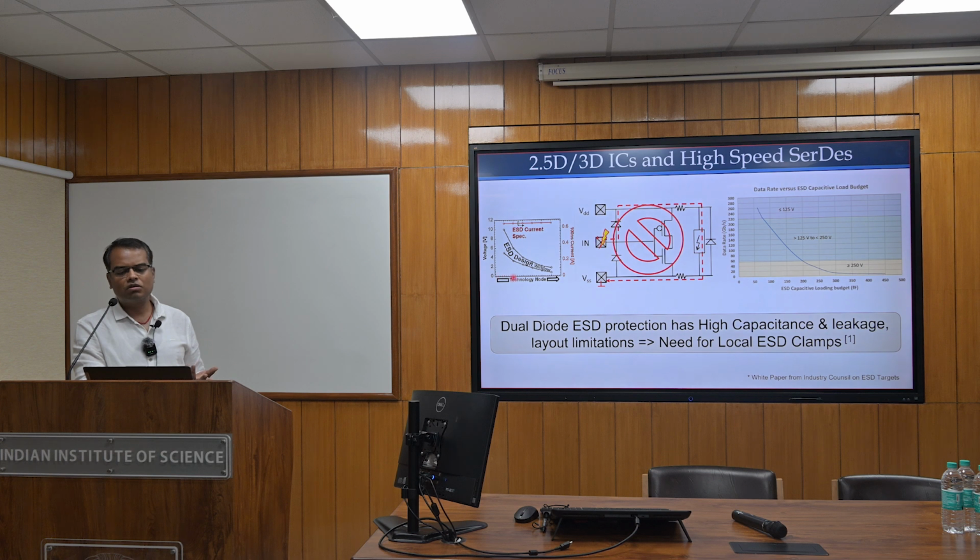As the technology node is scaling, the operation voltage is falling with each technology node. Also, what you expect from your security guard is to act before the damage is done, right? So this limit is the damage line, or the breakdown voltage, with each technology node.